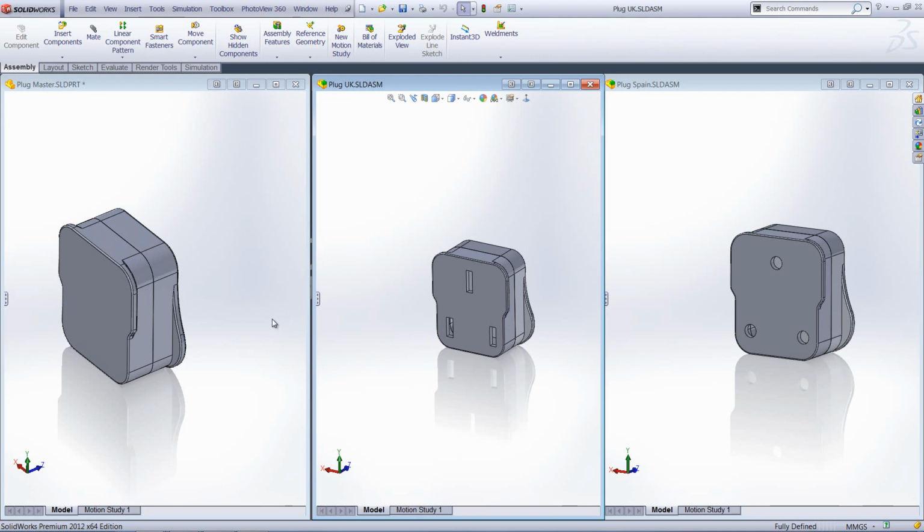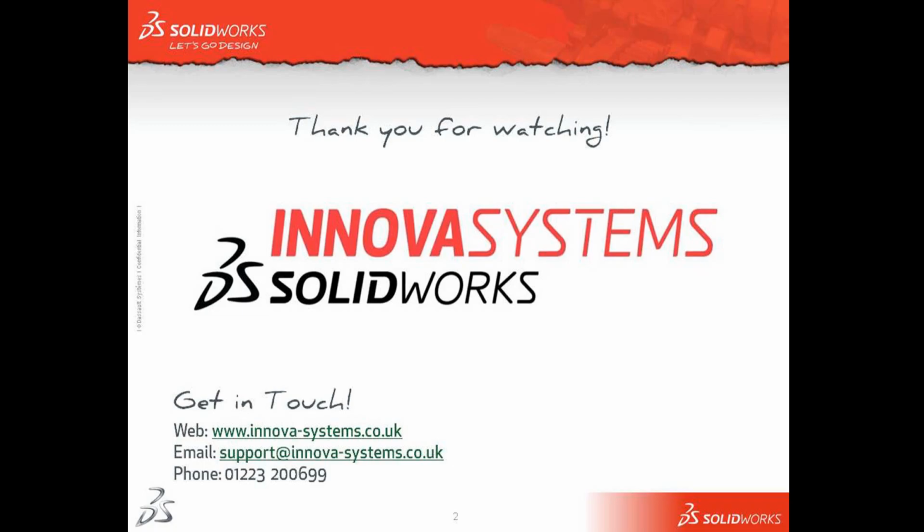So as you can see with this process, we can control the mass geometry of a generally standardized set of models, and this process can be implemented to drive a range of models, making small alterations to geometry only to the individual saved out bodies. So gross geometry can be controlled by that master document, and that is essentially the master model technique.